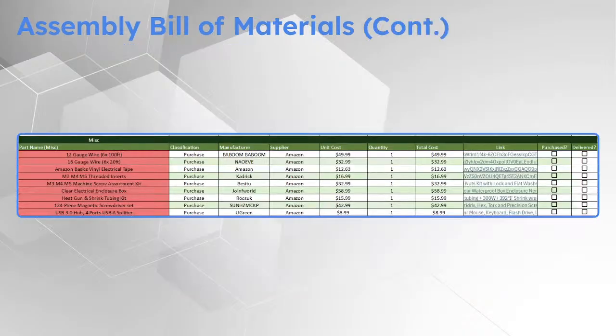All right, and then here's our bill of materials continued. This is just a lot of the miscellaneous pieces and parts, 12 and 16 gauge wire, things we're going to need to run power to the motors. Connor's going to go over this, but the motors do take the RS-485 communication protocol. So there is not a lot of fancy control work, like analog signals or anything that needs to go into it, which is really nice for the electrical side of things. You just hook up the signal wires and you should be okay.